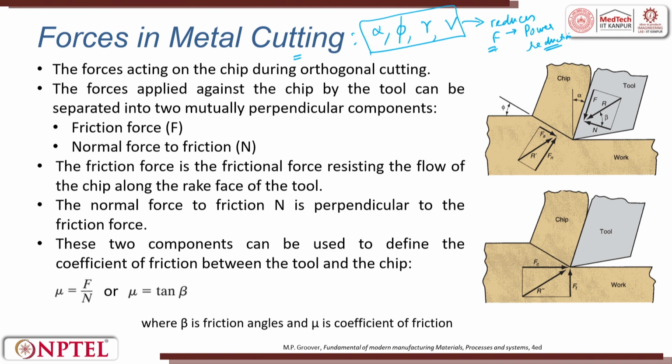Based on the force, I can go back and iterate all the parameters such that my power consumption goes low. So, now we are putting effort into understanding the force: how do I calculate the force with respect to the parameters which I give in the machine or make on the tool. The force acting on the chip during orthogonal cutting is shown here.